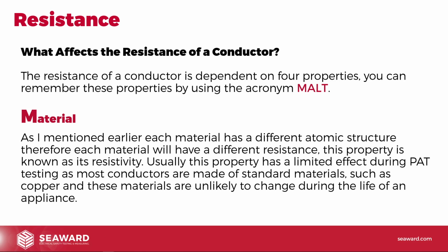And sometimes when you've got substandard or counterfeit products, you will actually see that it's a very poor quality copper, and it may have other materials mixed in with it, and that overall again affects the resistance, affects the resistivity. So you can see poor quality copper leads that have got very impure copper in there actually having a lot higher resistance, and that's due to the material, due to the structure of the material. So again, it can affect it, but it's not going to change over time.